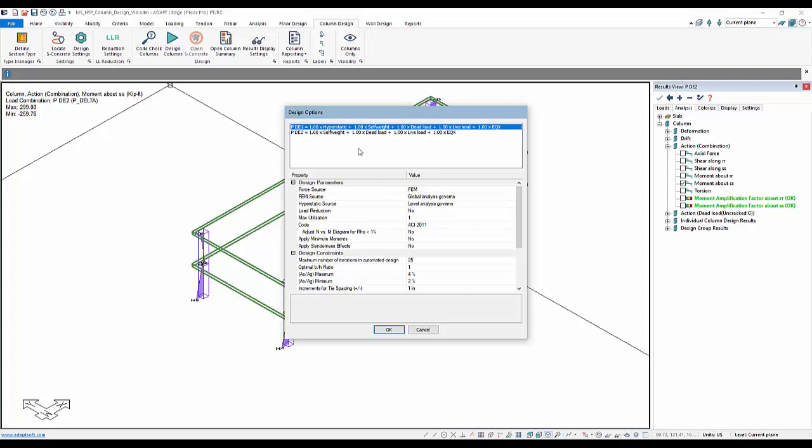that means that for self-weight, for dead load, and for live load and EQX, whether it's PDelta or non-PDelta, we're going to combine the reactions from the global solution that I just ran to comprise this combination. For hyperstatic, I could actually rerun the model in single level mode, which is more in tune with reality.